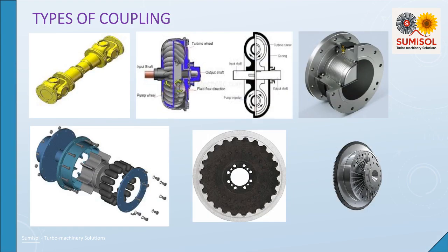This slide shows other types of couplings used in industry in specialized cases, such as the cardan shaft or universal joint, which is normally used with diesel or gas engine driven pumps. Fluid coupling where a mechanical soft start requirement is mandated. Over-torque slip coupling to protect the shaft line from over-torque. Hull-set type coupling to lower torsional stiffness to tune torsional vibration. Torsionally resilient type couplings, such as the Geislinger coupling, are normally used in diesel or gas engine generator sets to counter torsional ripples and protect the shaft line from high twist. These couplings are used in specific applications and are not API compliant.